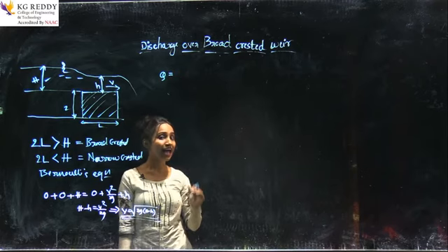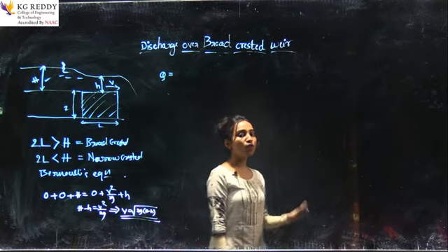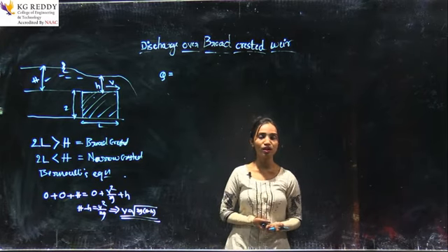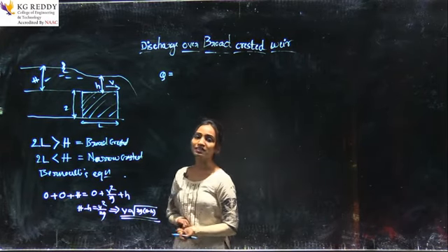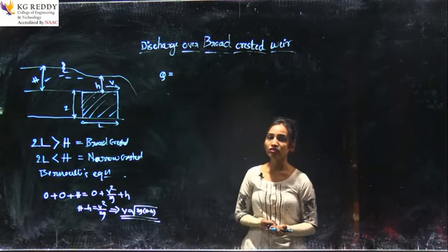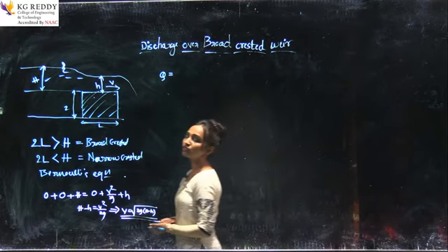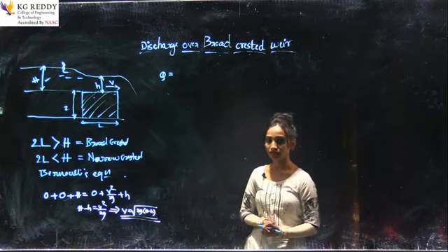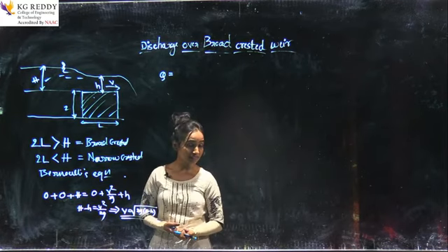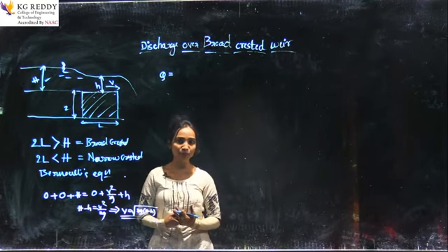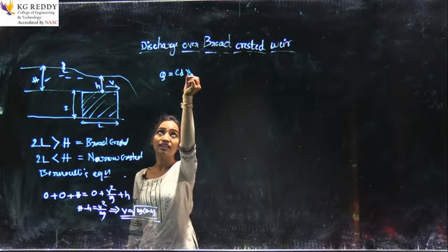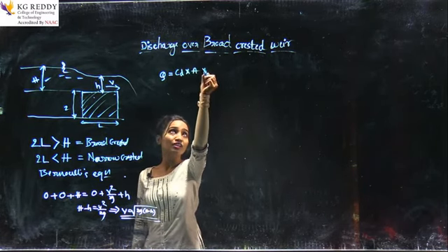The task I am giving: just glance yourself, what is the equation for the discharge? The same equations you applied in the triangular notch, rectangular notch, trapezoidal notch, and also in some devices like venturimeter and pitot tube, you apply the same. So discharge we are going to find, just glance yourself how we derived. Yeah, I hope you found the answer. The discharge we can write as Cd into area into velocity. Which area? Which is the broad one here.